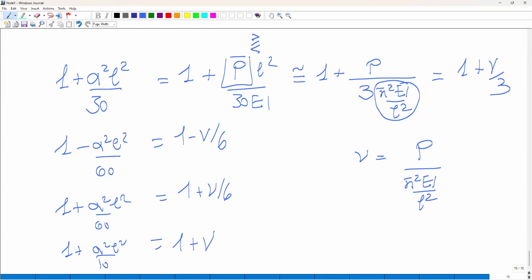You go there with mattresses, water mattresses. You fill them, and from the bottom floor, you measure the deflection. Obviously, you fill the water mattresses up to the service load level. So if your design engineer has said this slab is designed for this self-weight, which is already there, plus this live load, you just apply the live load.